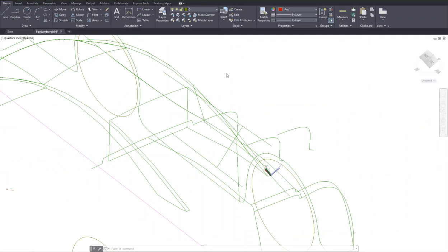All right, so at this point, we're going to create the other side of the side wall, so we're going to use the edge surf command. And for this side, let me show you what lines to select. First of all, line number 1, line number 2. Remember, we need 4 lines. 3 lines is not enough. And unfortunately, there are only 3 lines here.